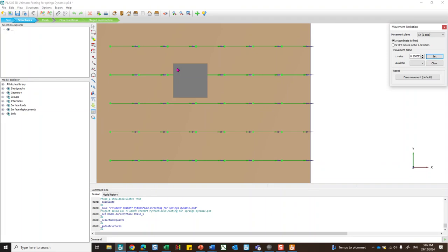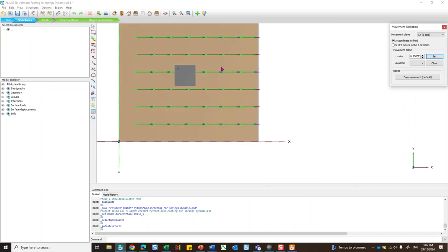You determine this and you extract it from the analysis, and then you give it to the structural engineer. And if you have, for example, a piled raft where the soil itself is carrying part of the load and the piles carry another part of the load, you should be able to see what happens and communicate these equivalent springs to the structural engineer.